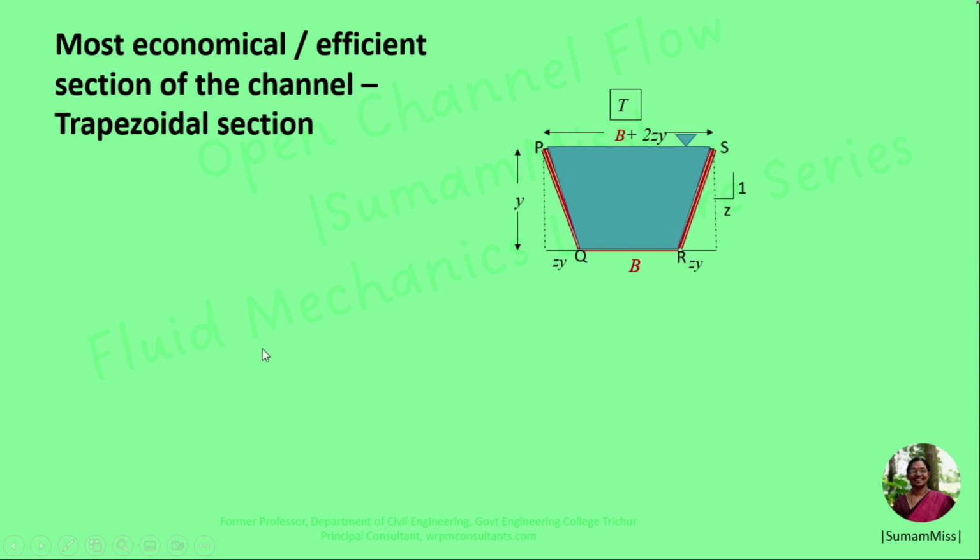The figure shows a trapezoidal section having bottom width B and flow depth y. Side slope is given as z horizontal to 1 vertical. So this distance equals zy, and this distance also zy. So the top width T equals B plus zy plus zy, that means T equals B plus 2zy.